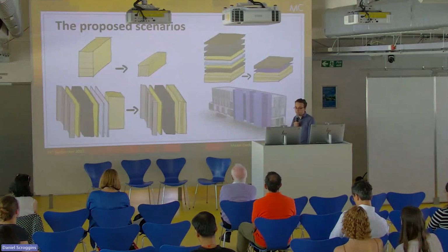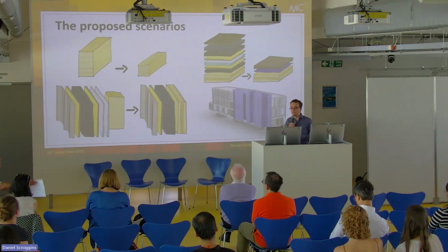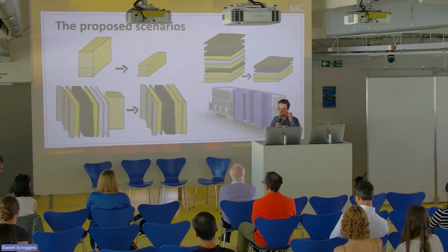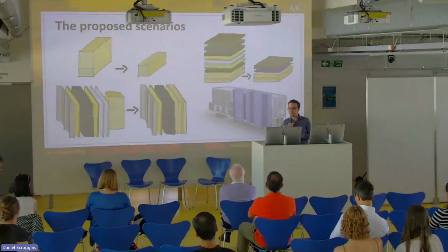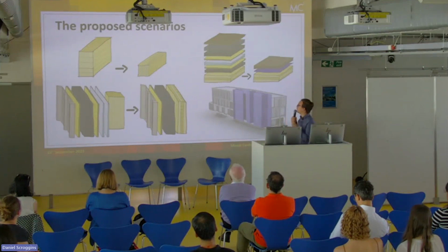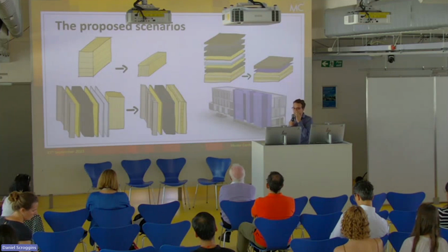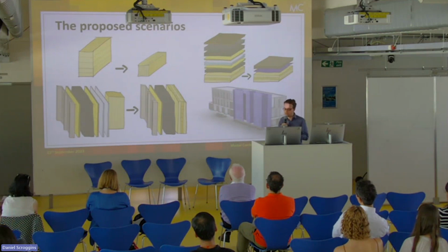So my proposed scenarios were focused on the structure, the internal slabs, the external walls, and the core, because in the structural frame, my main objectives were to remove steel and consider LVL, since it has these interestingly lower sections. And for the internal slabs, basically in the project, there's many layers in the construction elements. So I was thinking if we can get a good performance with CLT and a higher density low carbon layer.